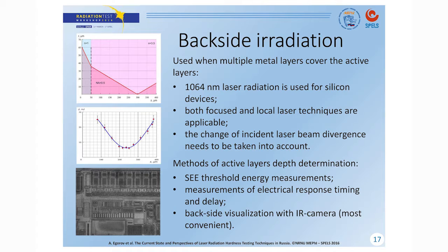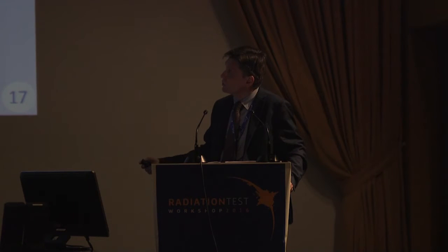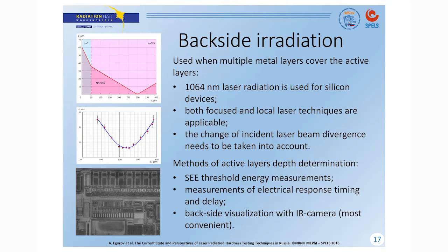This approach is based on the relatively small absorption coefficient of 1064 nanometer laser radiation in silicon. Both focused and local techniques can be used from the backside. For the local technique, an additional factor must be taken into account while determining the laser spot size, which is related to the refraction of the laser beam in silicon.